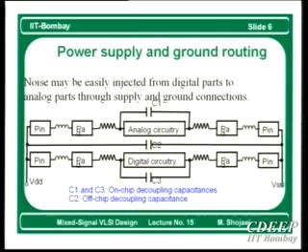See, for example, here this digital circuitry is injecting a lot of current into this inductor, right? Therefore, right from here, you will see a difference between analog VSS and digital VSS. They are not the same. And even if the analog also injects noise, these two are not the same. The amount of noise injected here and here are different. And of course, these coupling capacitances will reduce this AC current, because now they are also injecting the AC current.